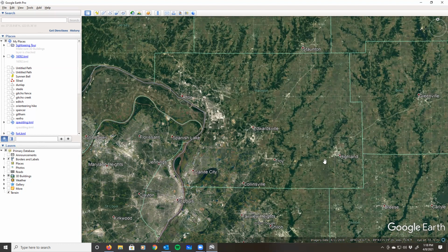It will use that along with the Geoid to create coordinate values, and as a result, everything you do with a total station will very closely match what's being done by GPS, because the two coordinate systems are so close to one another.